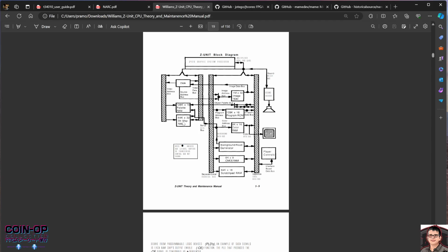It also helps me understand the bandwidth that's playing on the bus, right? So this system obviously needs a high level of bandwidth. So I want to understand how they achieved that. What did they do? Did they do bit replication? Did they do a literal huge bus width, like 32-bit, 64-bit? Did they use different types of memory, like an SRAM chip or a high-level SRAM chip? I want to understand how they achieved the bandwidth, because those are the data rates that we need to achieve in the actual FPGA core.